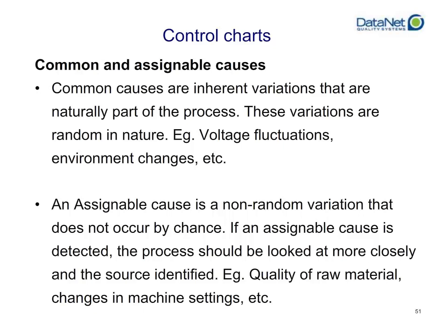Some examples of things that in a manufacturing environment could be an assignable cause include the quality of the raw material that you're using. One vendor gives you really, really good quality material. The other one gives you really bad or questionable quality material. And you see in the output of your process that all of a sudden there's a shift. One material you're running really close to target, and the next material you're all over the place. So that might be a source of an assignable cause.